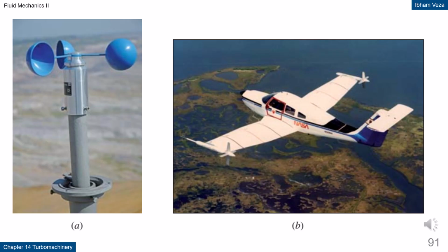Nutating disc flow meter. This figure shows the internal cutaway of the device to illustrate how the fluid drives the disc motion. The flow path and disc movement mechanism are displayed to clarify the working principle. Each disc motion is converted into a mechanical signal or a numerical reading. This visualization helps explain that the measurement is based on discrete volume, not flow velocity. This is why the device remains accurate even at low flow rates.